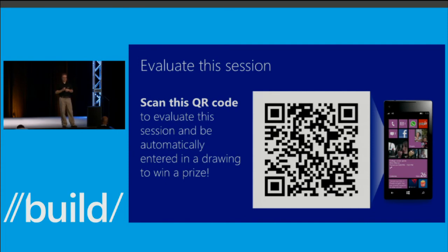Is there going to be any way to control the tessellation and say, here is how I want these lines tessellated? No. The tessellation is all done by D2D for you. And it's based on, I didn't get into it, but there's basically a tolerance factor that you need to specify that tells you how close the realization needs to be relative to the actual geometric definition of that curve.